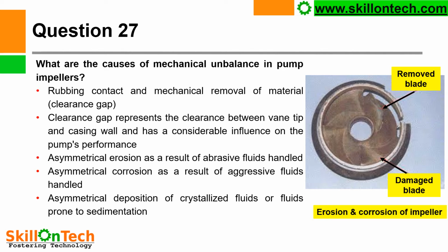Asymmetrical erosion as a result of abrasive fluid handled. Asymmetrical corrosion as a result of aggressive fluid handled. Asymmetrical deposition of crystallized fluids or fluids prone to sedimentation. If fluids are prone to sedimentation, then they will deposit on the impellers or rotating components and will create an unbalance that may cause heavy vibrations in the pump.